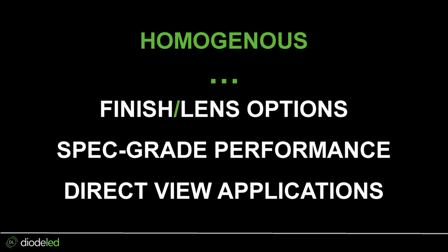You can have a low profile channel, okay, and you have dotless lighting, but it can still be so low profile that the lens is too close to the tape light and you get a hot spot, a beam through the middle, and it dies off on the sides. Homogeneous lighting is having even illumination from the edge of the lens to the other edge of the lens completely.